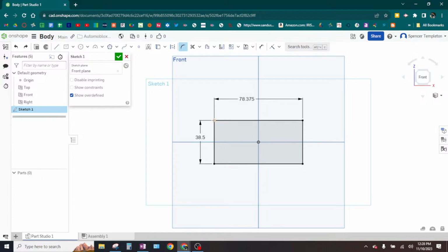Watch here. If I place a fillet, fillet, fillet, fillet, we can do all four, and then after I've done all four of them, I left click off here. Do you see how there's that green check mark on the mouse? But only if I'm way over here. Now it knows, or assumes, you want all four of those fillets to be the same size.